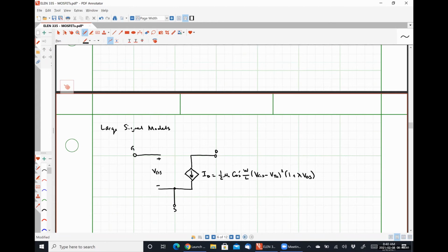We're going to see that the input impedance for MOSFET transistors is astronomically large usually for this very reason as well. There's a capacitor in there messing things up for us, or really helping us out if we're looking for large input impedance.